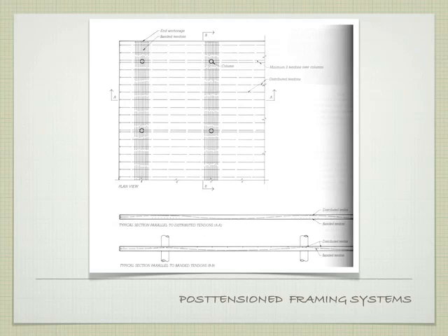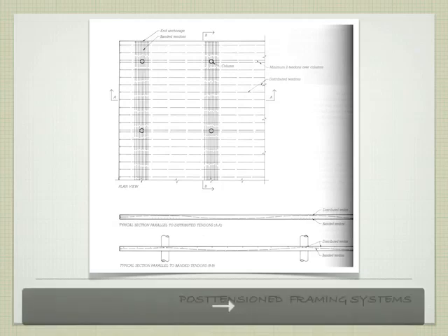And so the nice thing about this is that we can deliberately drape the tendon so that the reinforcing is at the bottom at the midspan, and at the top at the column. So we're using this more efficiently than we could normal rebar, because it's flexible like this.